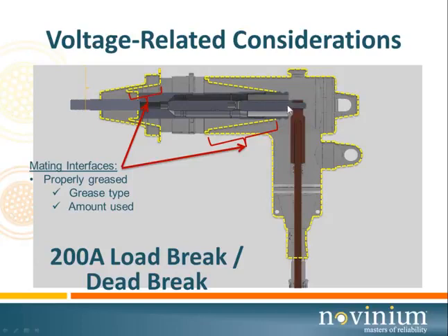The bigger problem is using too little grease. And that comes down to whether it's uniformly distributed and uniformly applied. And again, this interface, the operating interface, the interface that you're going to rely on to be able to be operable for the next 40 years, you want to be able to remove it and put it back on.